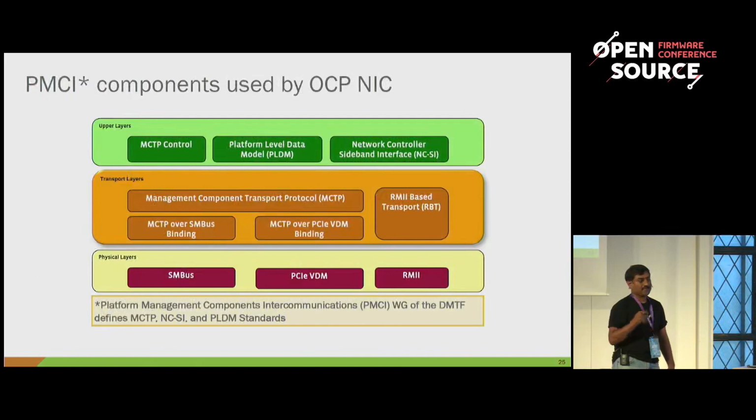And thanks to the DMTF, we don't need to invent the protocols to talk between the BMC and the NIC. NICs are made by so many vendors, so it's better to have standards. In this case, DMTF came up with the PMCI standard that has multiple protocols that allow us to monitor it and update the firmware. All these protocols are well understood by the industry, so it's easy for the BMC to adapt to this.